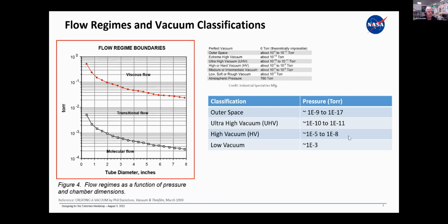And then ultra high vacuum, which we saw some of the situations on the moon, you could easily be considered into an ultra high vacuum or UHV environment versus HV. And that's really important, and I'll explain in a moment why we can test on Earth and justify, say, testing in high vacuum, even though our true environment might be ultra high vacuum.